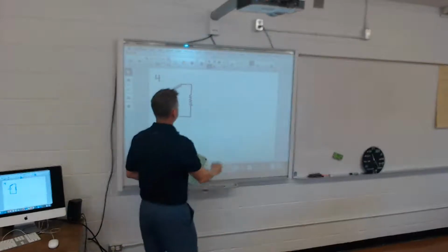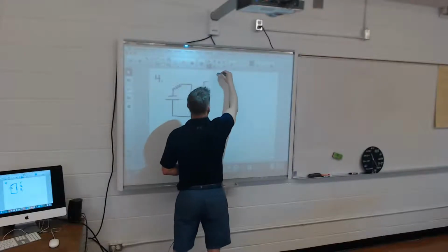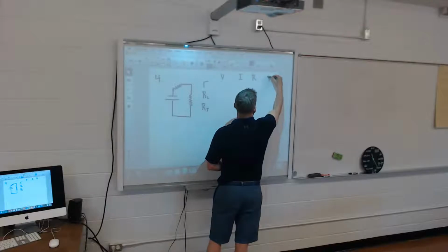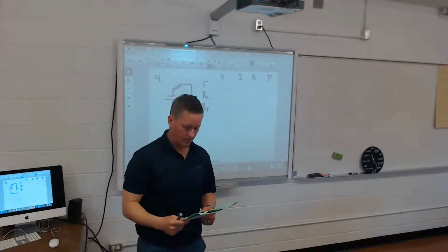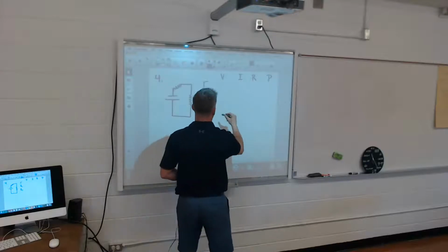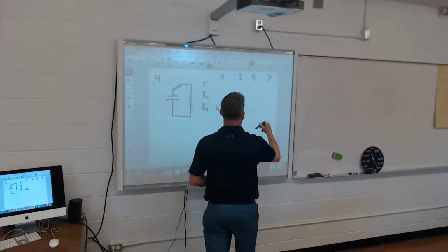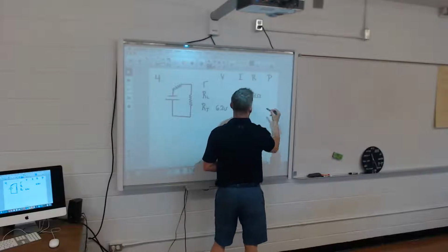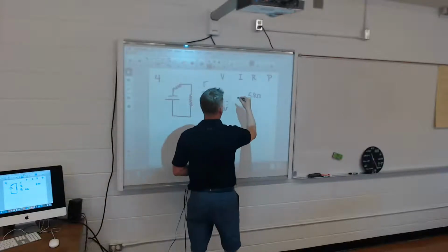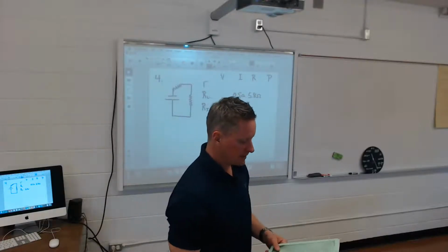Simple load resistance set up. Two dry cells connected in series provide an EMF of 3.1 volts each. So that's a total voltage of 6.2 volts. When a load of 5.8 ohms is connected across a battery, an ammeter in the external circuit reads 0.5 amps. Find the internal resistance of each cell.